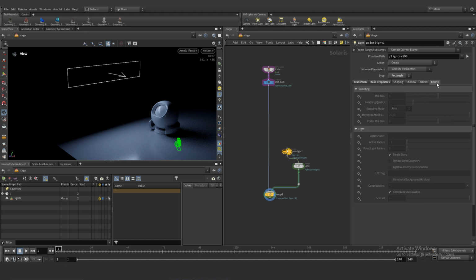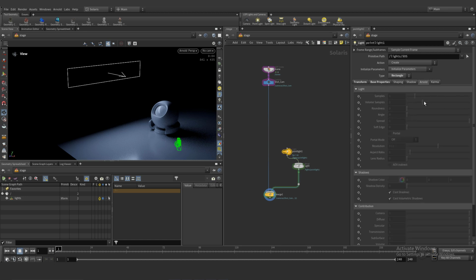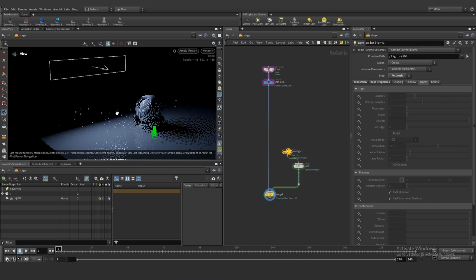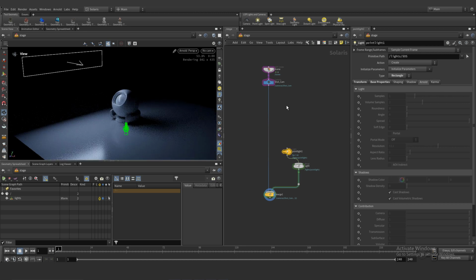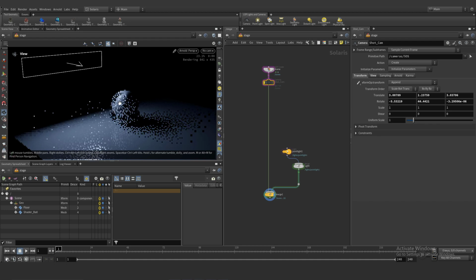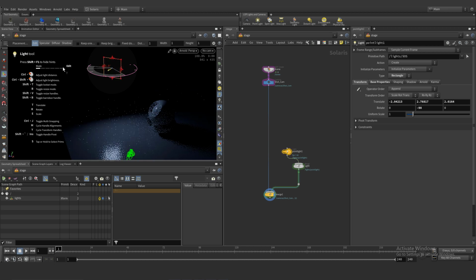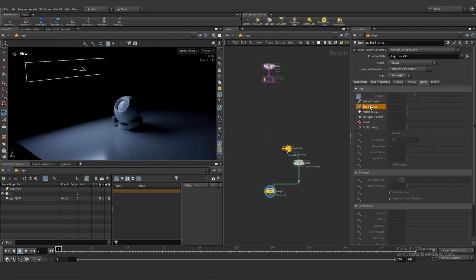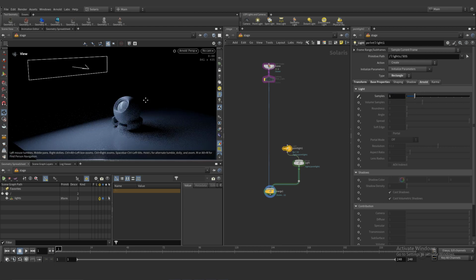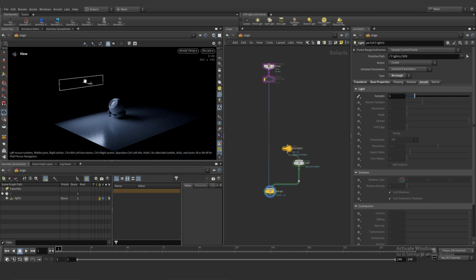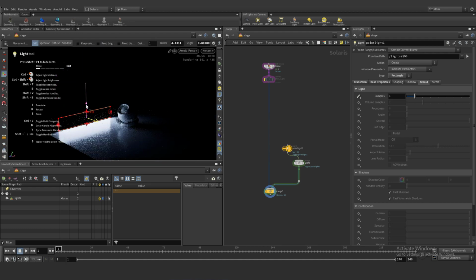And if we use Karma, we can jump here, but we can use this. We use the Arnold renderer, and that's why I jumped into my Arnold parameters. If we activate this parameter, we choose set or create. This is our light samples, and it cleans our shadow. You can see this is very noisy, of course, and 3 or 4 is a good value for productions.